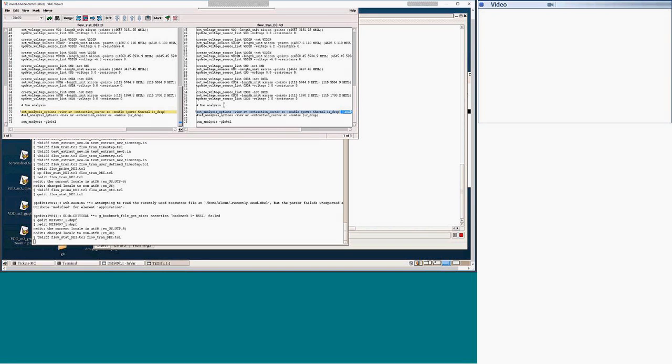So the first step we saw yesterday with the prime run, when we ran without any circuit ready. It was just a very rough check. Then the second level is the static run that we do right now. And the third type is the transient run, where you see the actual waveform profile, and you can detect peak voltages, and you can see your temperature increase in dynamics, in a very short period of time though, because you won't run the simulation for 15 minutes, I'm afraid.